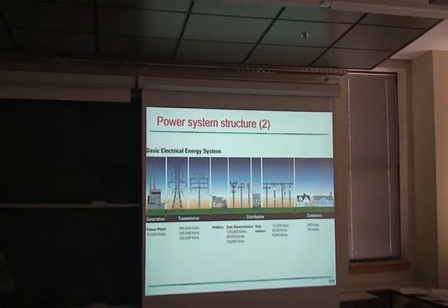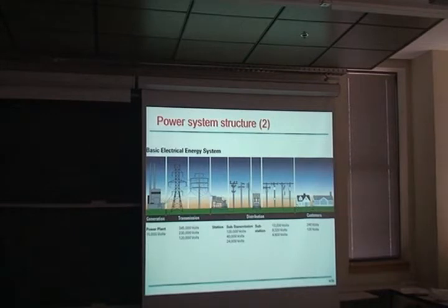The other place where you do find DC is where it has to go underground, because AC at high voltage, for various technical reasons, doesn't work underground. So if you have undersea cables for a relatively long distance, then they'll probably be DC. There's been a new DC cable installed underneath the San Francisco Bay to get electricity into the San Francisco Peninsula, because there just wasn't any spare space to put new traditional power lines in there.